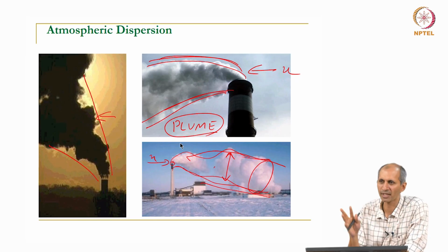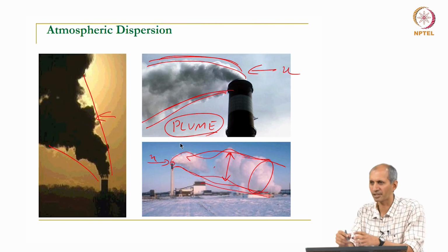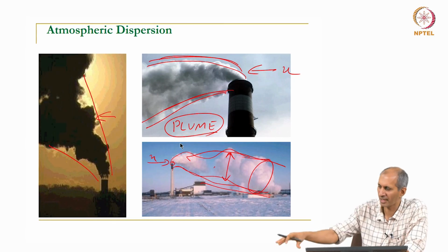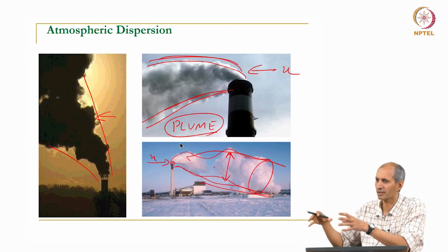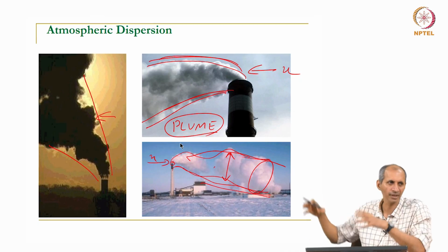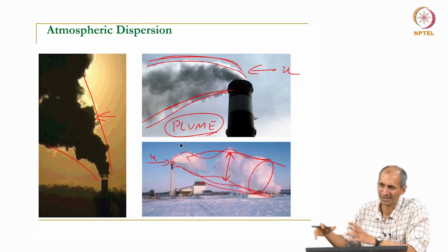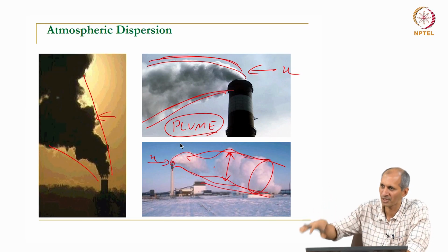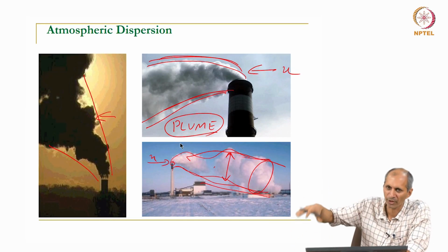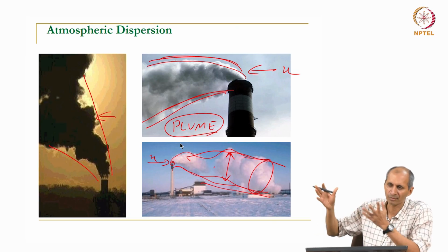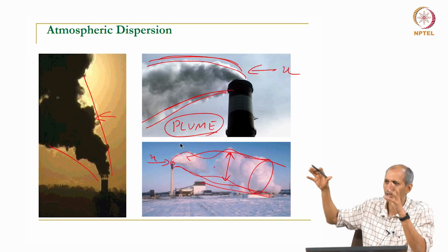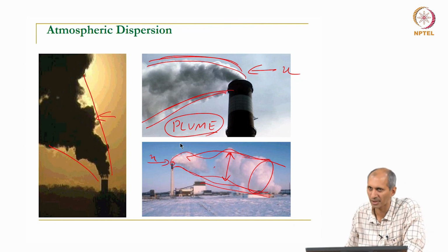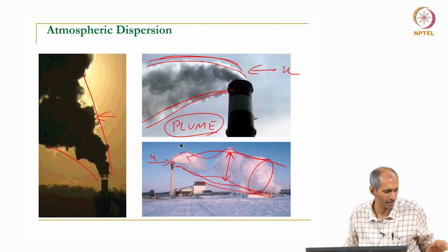If there is no mechanical force, no wind, nothing will happen, it will just sit there and grow. Imagine there is no wind and I light a fire here, you will see that it will just grow like this, and it is only the diffusion process and buoyancy that is happening, no other convection. The mass is moving by buoyancy, and buoyancy also stops at some point when it comes to equilibrium, and then it will just sit there and move slowly by diffusion. So we will look at all that. We will stop here today.